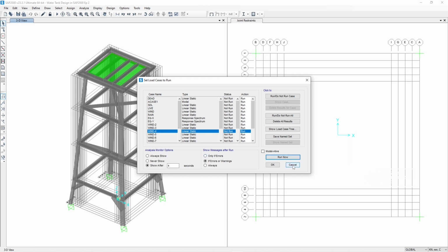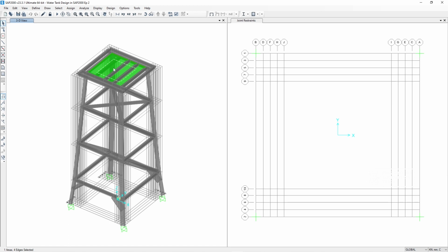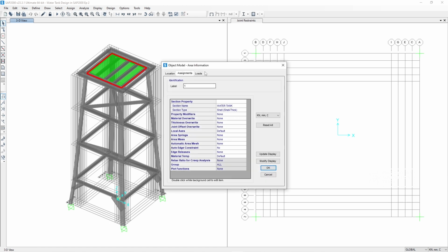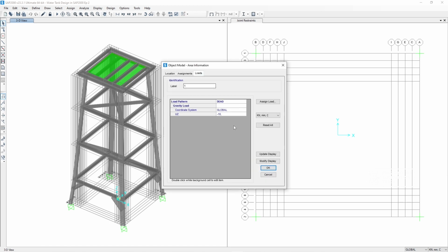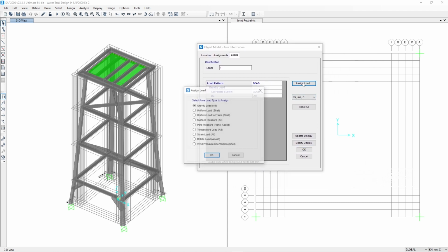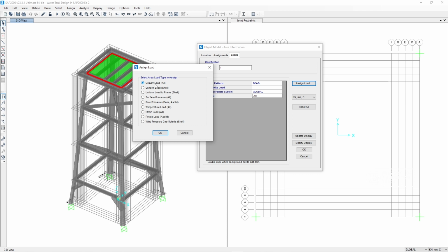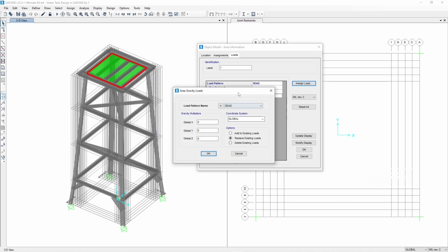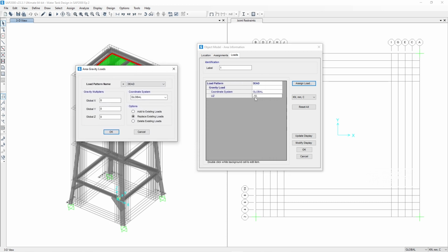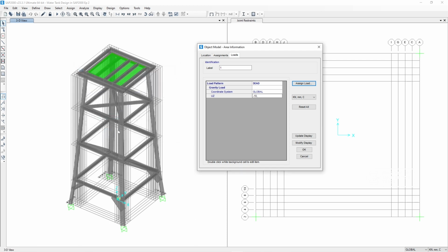Oh yeah, I just forgot that we haven't put the load here. Let me make sure of this one. Let me go to assign load, grab the load, okay, and then we replace the existing UZ, which will be equal to maybe 10 kilonewton per meter. So it will be defined.